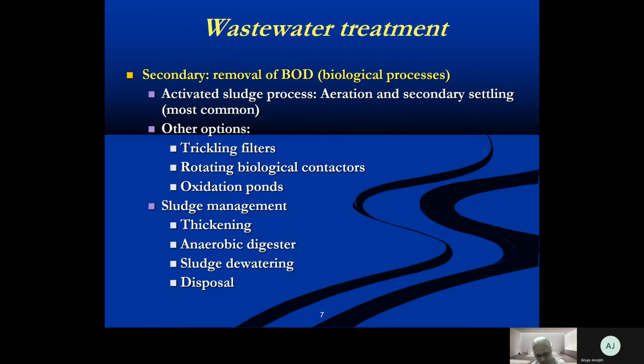I should also mention at this point that biomass is difficult to remove. I've already said that bacteria are biological particles, they are colloidal in nature and so on. But when the concentration of biomass increases the way it does in the activated sludge process, bacteria are sticky colloidal particles. They stick together, they form large flocs, and these large flocs are easy to settle in a secondary clarifier.